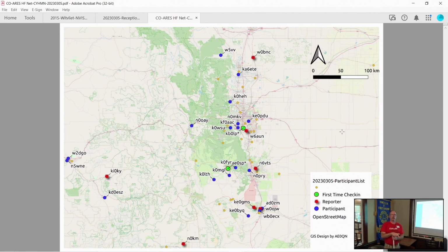Marty had a question. You're using a tuner with this, right? Yes, and I started with a manual tuner on purpose and a nano VNA to make it easy to tune up. Because with a manual tuner, I could see what's going on, and I could see how touchy the antenna is, how critical it is, how much bandwidth I have before I have to retune.